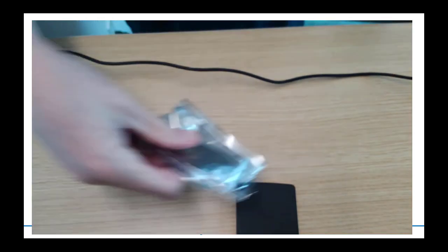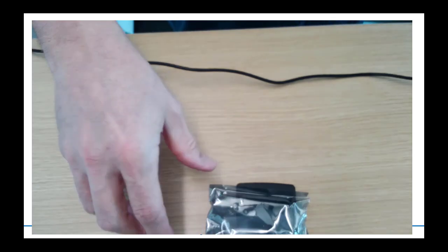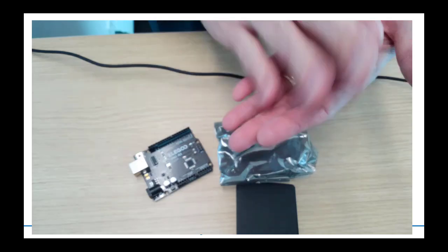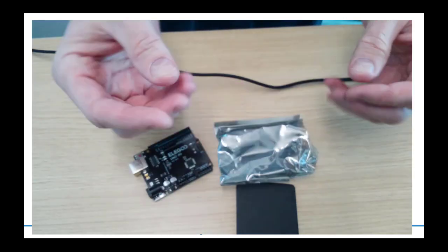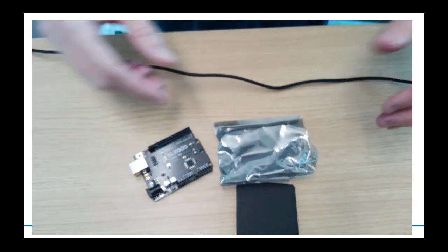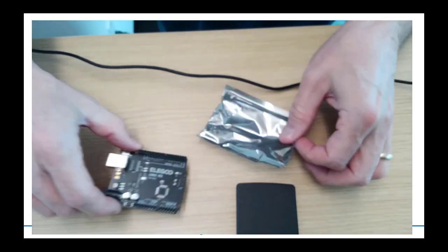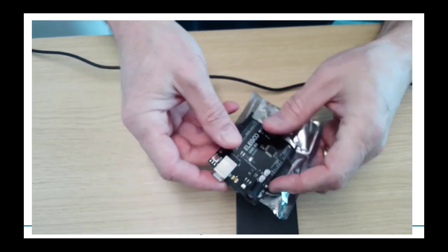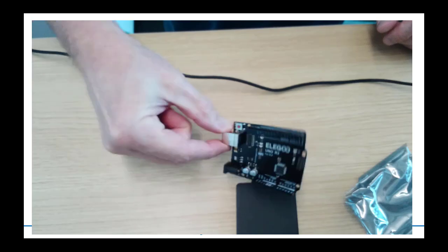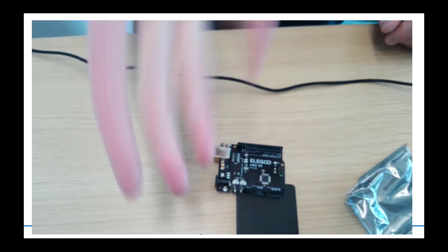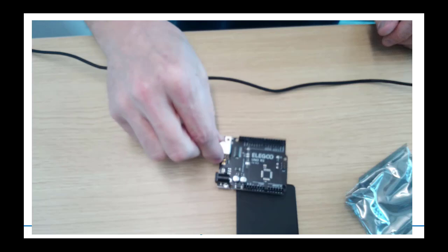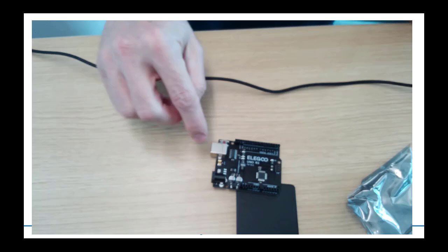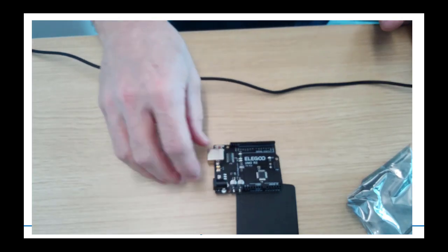Okay, so now here is a little bag that it came in, and here's the Arduino, and you're like, what's the bag? The bag is an ESD bag. So if you have a cat or you walk across the carpet and get charged up and you zap electronics, it kills them, right? So one of the things you can do is put it in a bag whenever you walk across campus or do anything, and then that way the ESD doesn't build up. Another trick is to always grab the USB cable, the USB connector that's ground. So if you are charged up, been petting cats, you go ahead and grab that, and hopefully all the energy that you have on your hand from petting a disgusting animal is zapped into the ground plane, and you won't actually blow that thing.